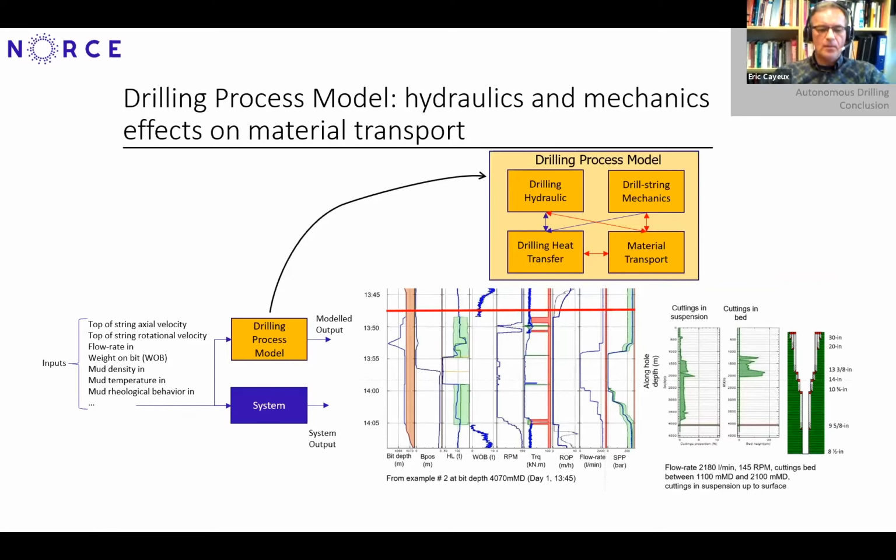And you can see here for this particular well, which is, as you can see from the wellbore architecture, a tapered architecture. It was necessary to have a very large hole size to put a submersible pump, because it's a very depleted reservoir and we need a submersible pump to lift up the fluid.